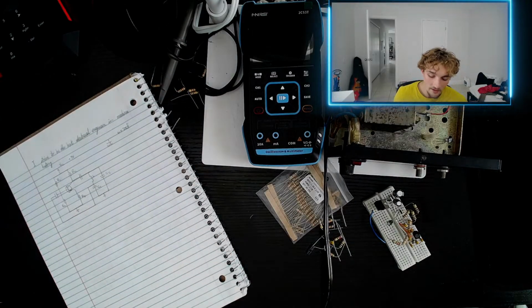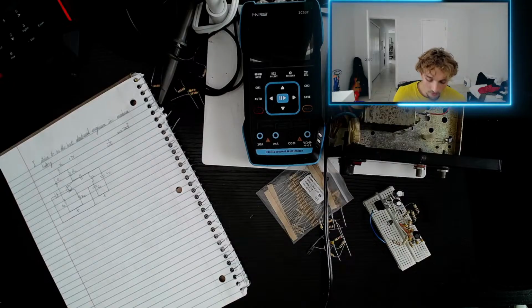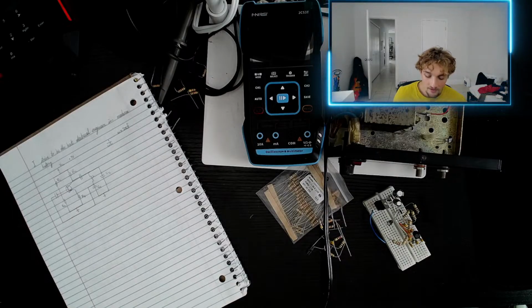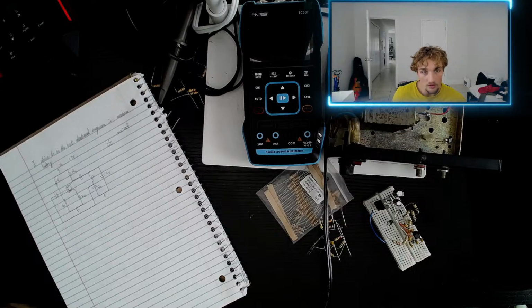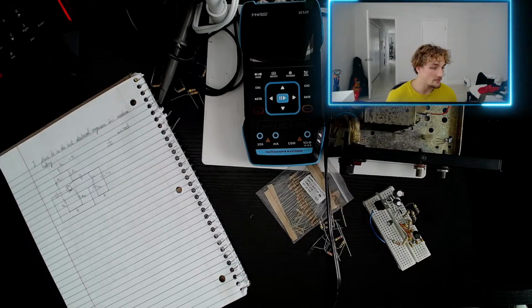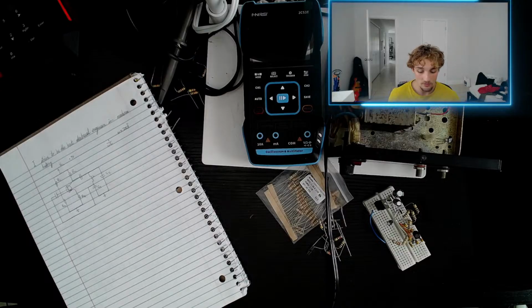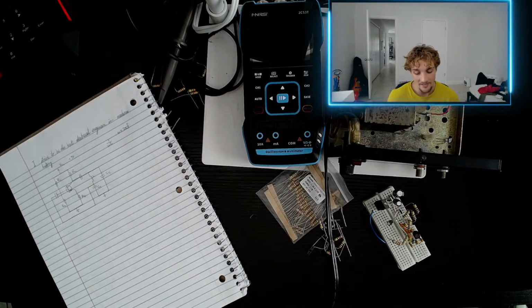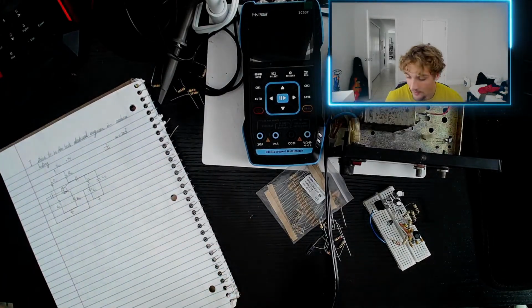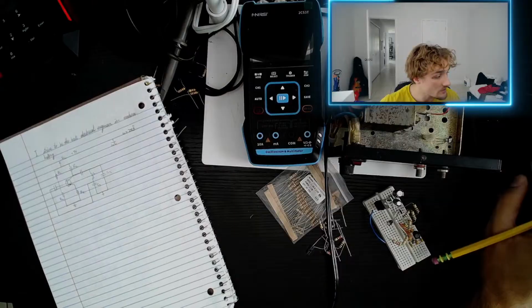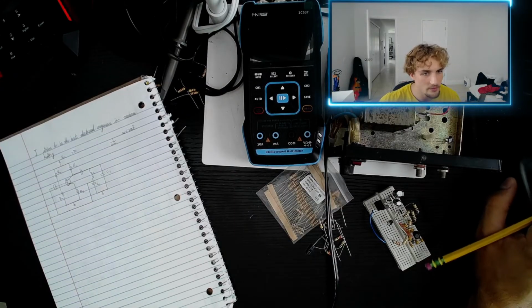Therefore, the lower the frequency, the higher the impedance. The higher the frequency, the lower the impedance. So with a low frequency, such as DC, we're going to have a high impedance, and this will not pass through. It's attenuated. So that relationship defines exactly why we add those capacitors there. I need to zoom in just a little bit.